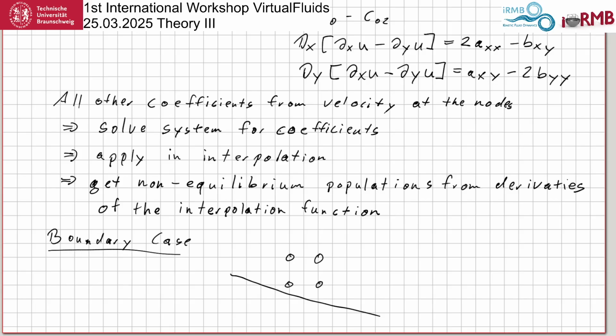So this is your coarse grid, and say we have a fine grid in between, and you have your grid interface directly cutting into a boundary. So then these things, maybe I draw them in a different color. You would like to interpolate these red nodes. So say these are the destination nodes.